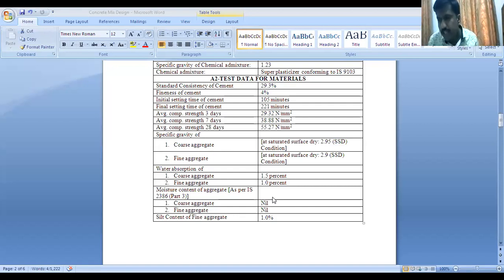the cement starts gaining strength. It will harden up. It will start hardening. It will start gaining strength. Why? The heat is liberated and it starts gaining strength. That is why we have to prepare the cement paste quickly. Whenever we use cement for testing purposes, that is, for finding out the physical properties, we have to mix the cement within only 2 to 3 minutes.